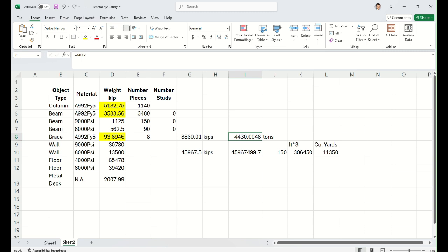They have to consider probably 10 to 15% more, because they know the beam they procure is 30 feet, but they need to cut it, depending on their length. Some of it is lost, right? Obviously, they consider 10 to 15% more for their estimation, as there is always loss because they need to cut it.